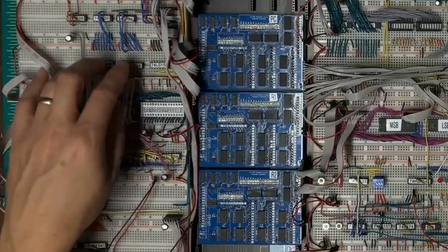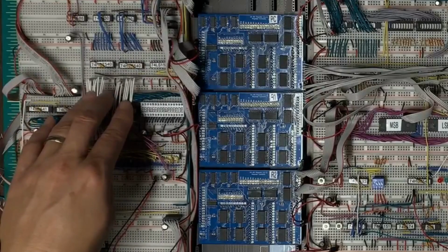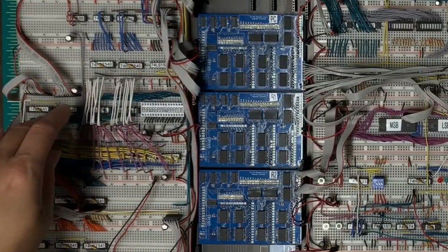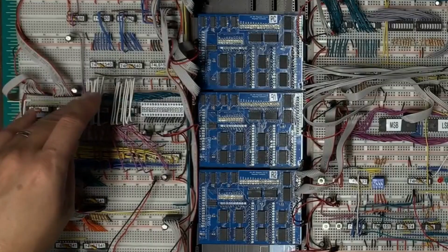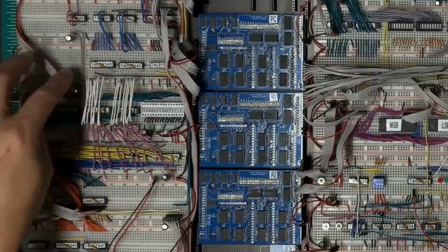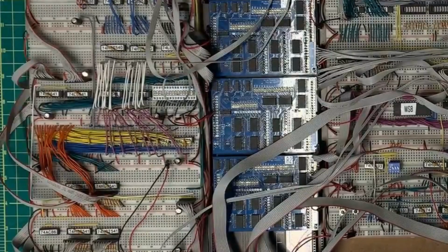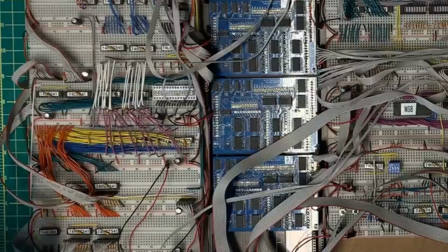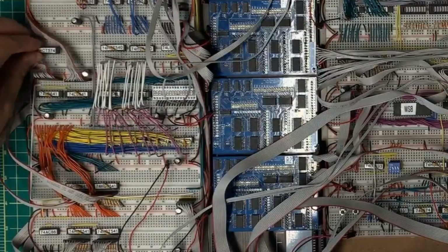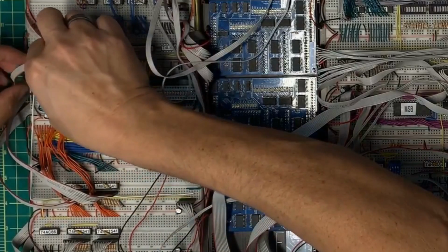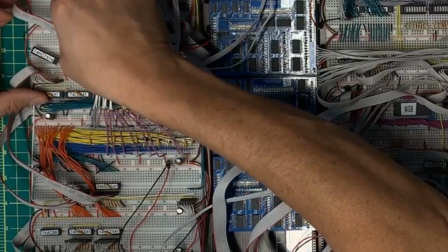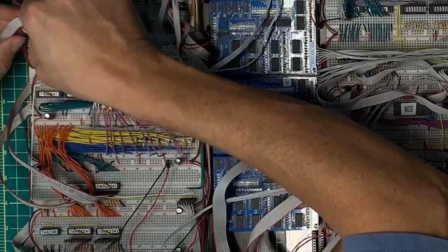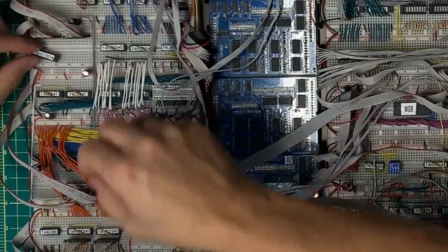The pickups for calculating the Z flag, which are here, all need to come after that line driver, which is going to be whatever's on the ALU bus. So that's going to change as well. Okay, let's see if we can get into the changes here somewhat systematically so I don't make a complete mess of this. I want to put the latches up here, which is going to change where I pick up the main bus. So let's move that first. So that should be there, and that should be there.